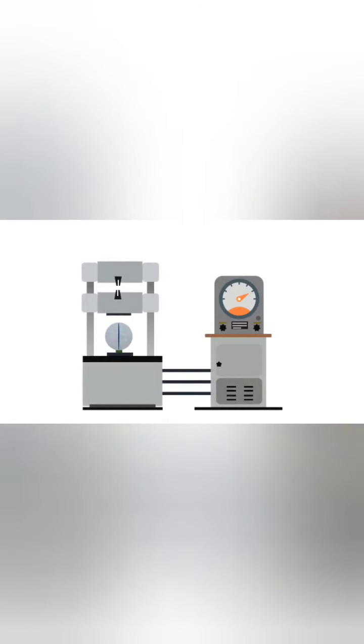The specimen is placed longitudinally in the machine. A bearing strip made of plywood is placed on both sides of the specimen and aligned according to the marking. Sometimes, supplement bars are placed on top of the plywood depending upon the diameter of the specimen. Now, apply the load continuously at a rate within the range 1.2 to 2.4 MPa per minute. Finally, note down the load at which the cylinder fails by developing cracks.